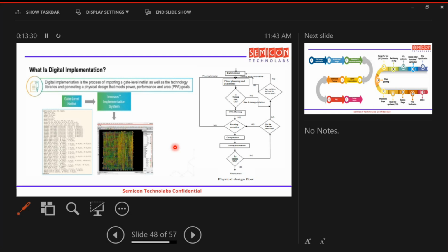The reason being, our main criterion is to reduce power consumption, because the majority of devices we manufacture at that high cost are battery operated, and we need battery life to improve. That's where we go with FinFETs. In CMOS there is some leakage power, and that's the reason they want to minimize it. Correct, you are right, exactly right. So power consumption, dynamic power and static power, is the main criterion, and that's why we are going into FinFETs.